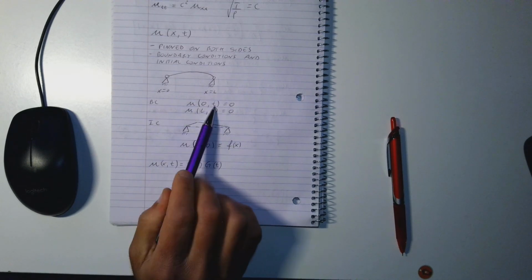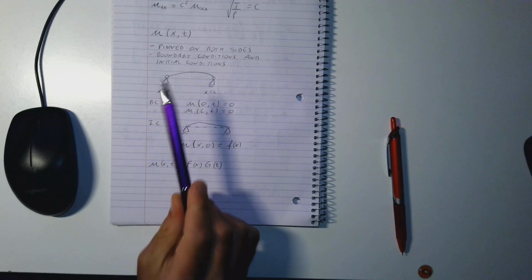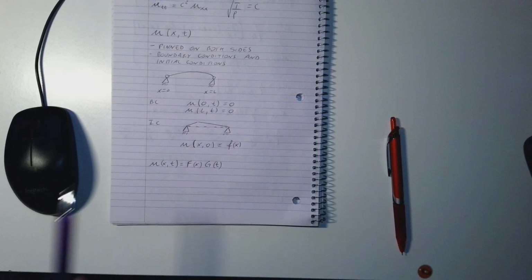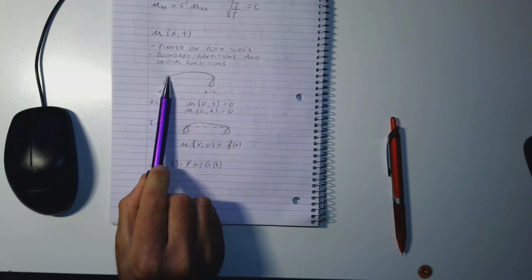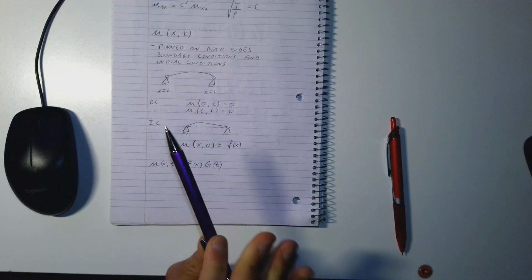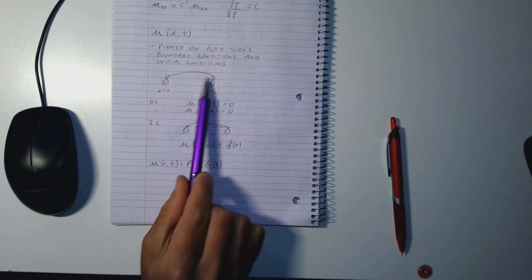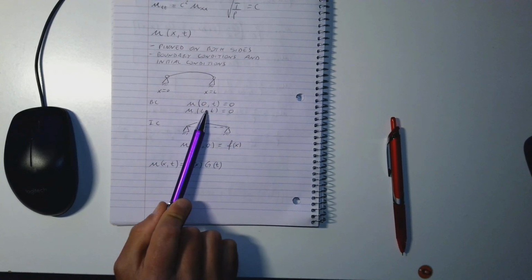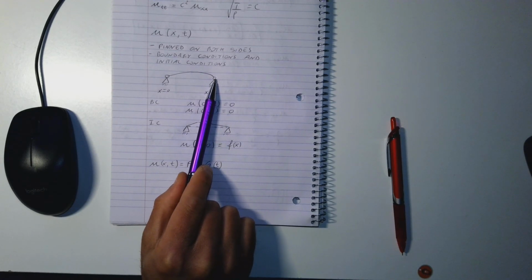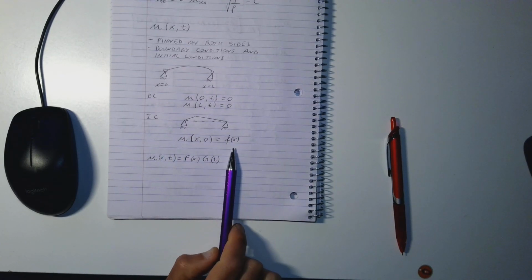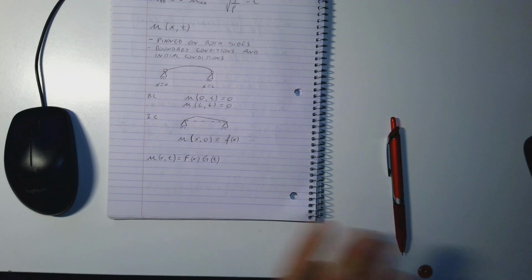So here, when we look at the boundary conditions, these are conditions that are related to specific points. Because you for sure know that at any time your displacement here and your displacement here will be equal to 0. So that's why they are called boundary conditions. So these are two conditions that are related to what's going on at this specific point and what's going on at this specific point. When you look at the initial condition, it means that you are basically removing the time, because you are saying, okay, let's see what happens at the beginning of my study, of my timeline, right?